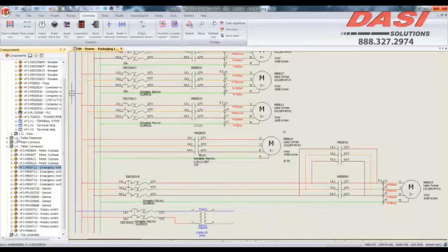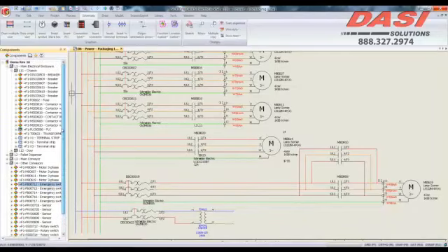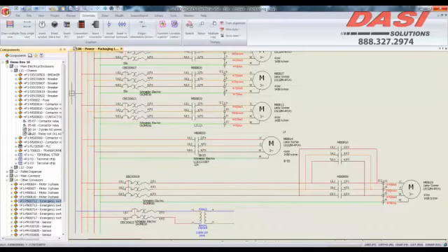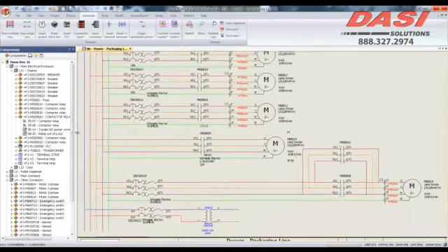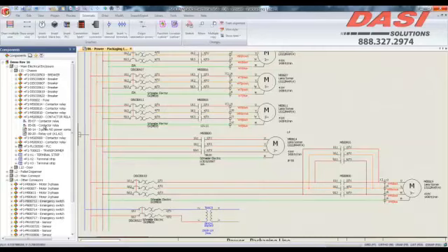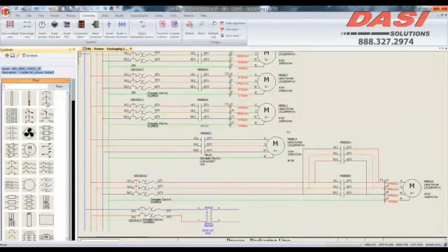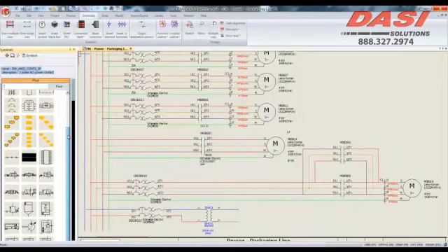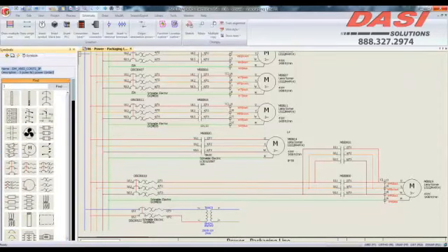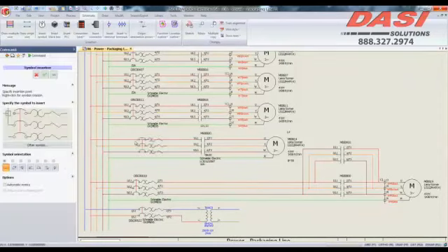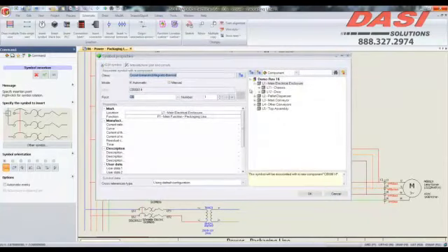I can see from the component tree that I have that information right here. So here is this relay 820, and now you can see that I've got the 3-pole contacts as well as the relay coil. It's also being used in a couple other areas here. I can continue to add more symbols just by grabbing them right here. As you can see, I've got a 3-pole. I am searching by the number 3, which of course becomes very easy to find some of these components, especially if I'm working all in the 3 phase.